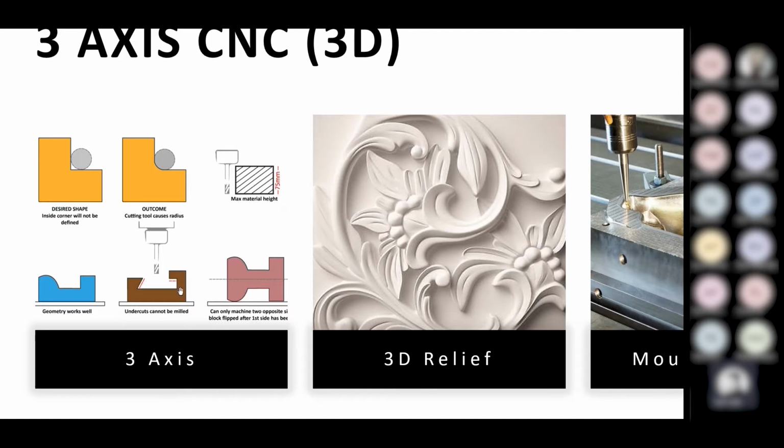It can't cut underneath. If you had a 5-axis CNC, then it might be a different story, because a 5-axis would allow you to rotate the model as well. So not only rotate the tool bit, or the mill bit, but also the model, and you can start getting into these little areas. But again, try and avoid undercuts where you can.